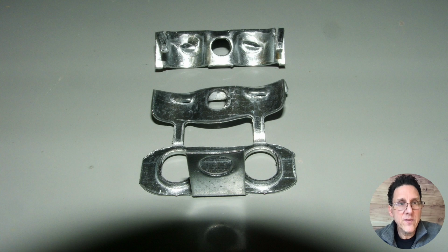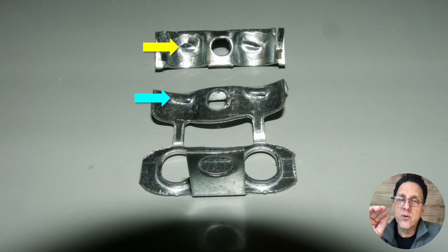All right. The top one and then the bottom one. Now you can see, especially those bumps, right? If you pay attention to those, the way the bumps are made, the top one, it's kind of got a smooth edge to it, right? So the top one is meant for NM cable, and the bottom one is not. The bottom clamp is suitable for MC cables, probably AC cables, maybe flexible metal conduit.